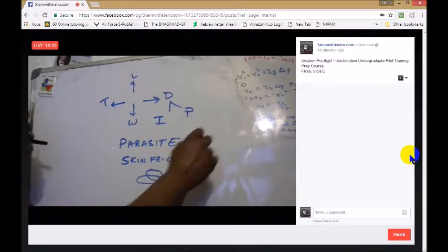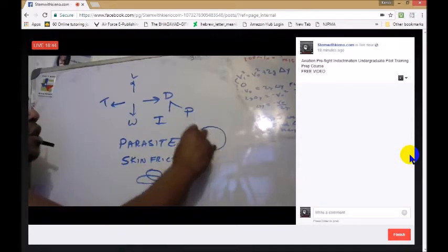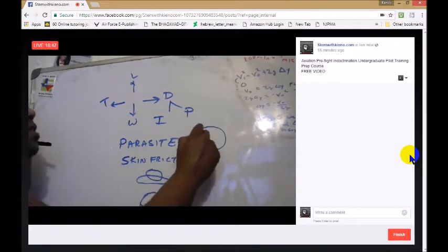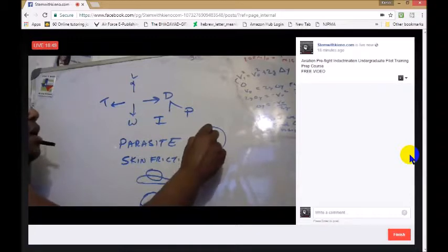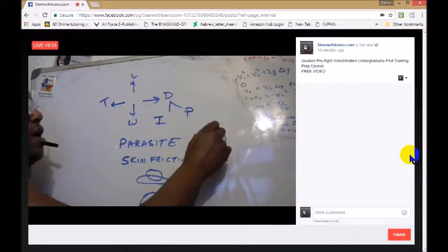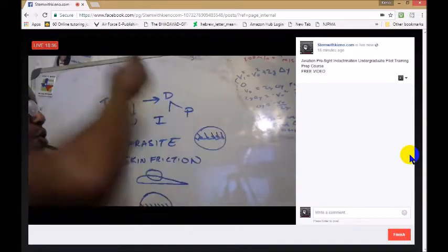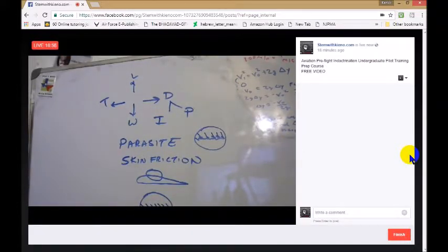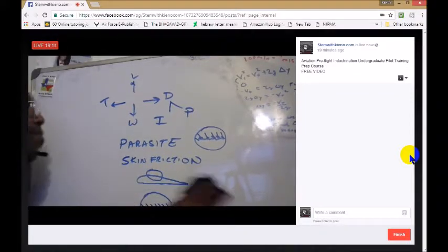And I'm sorry, I should have brought that up a little bit. So here's our microscopic view. I just looked at the camera and noticed. If we put this under a microscope, there are little spots or ridges that air can be trapped in. All right, so that is our skin friction drag. Let's talk about another component. These 3 components all total parasite drag.